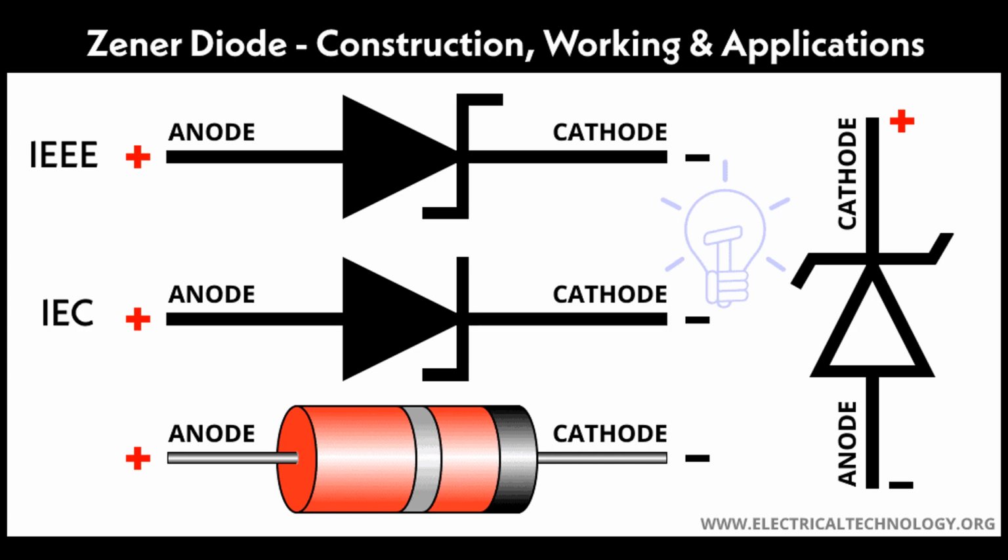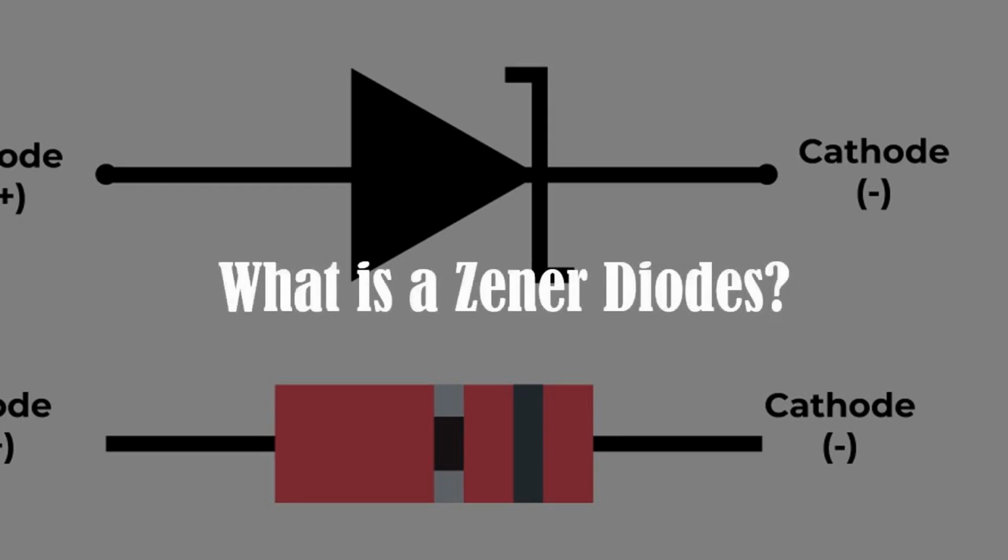4. Voltage shifting. Level shifting. Zener diodes can shift voltage levels in logic circuits, allowing compatibility between different logic families or interfacing different voltage levels. Biasing circuits. They are used in biasing circuits to set a specific voltage level, often in amplifier or comparator circuits.